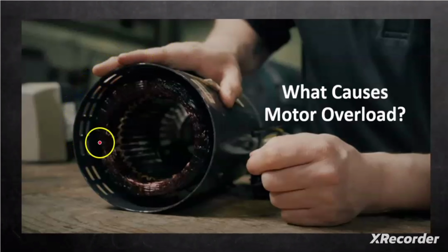The problem arises when the motor, due to any reason, is taking more than its rated current. When the motor starts taking more than its rated current, then the motor generates more heat, which cannot be dissipated at the same rate as when the motor is taking normal rated current. So that will cause the motor overheating, which will lead to many critical damages to the motor.